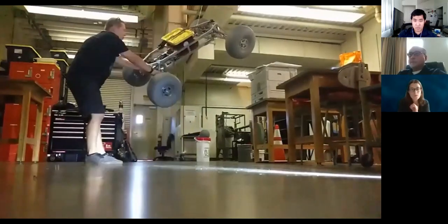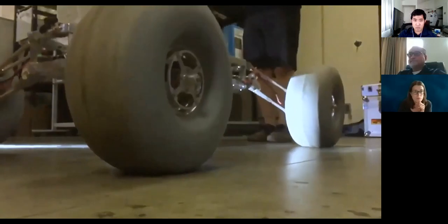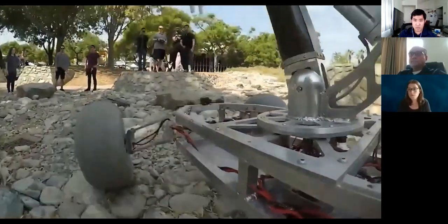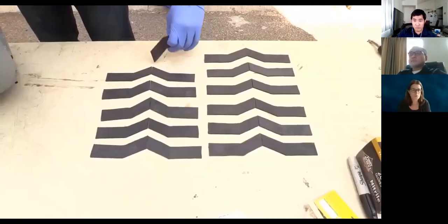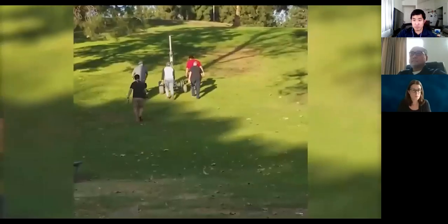Beyond the lessons we learned from last year's competition, we decided to put the mechanical system through a series of rigorous tests to determine key locations for weight reduction to increase rover functionality. Testing provided valuable information, verifying that our system is robust enough to tackle any difficult terrain that is featured at competition. Dual brush DC motors are mounted into each custom hub assembly in order to shield them from rocks. The tires have a custom tread design in order to increase our traversal abilities across sand, dirt, as well as steep slopes.